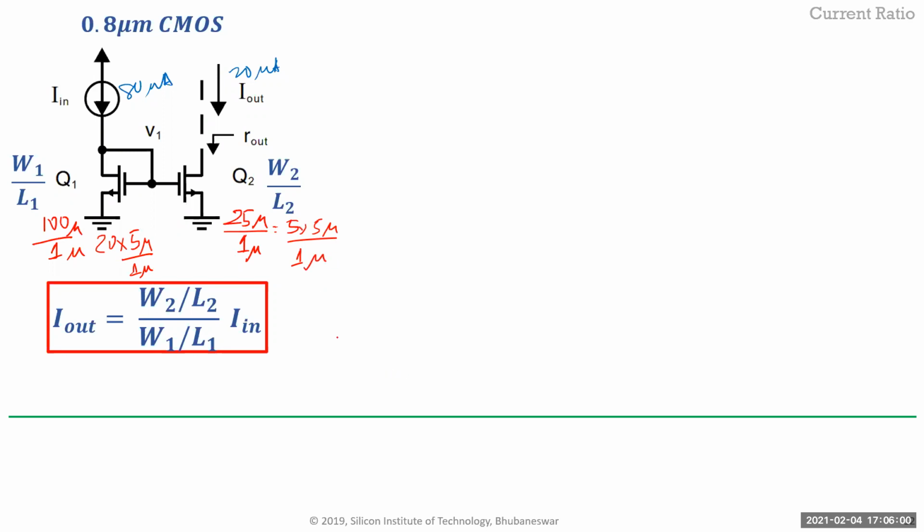That way, when you do the layout, you take a single diffusion, you start interdigitizing, doing common centroid and all that. So that mismatch I was talking about, that delta VT mismatch, will be minimized when you do that. Okay, so you're always going to work with unit transistors, unit resistors, unit capacitors. You're never going to do one big cap here, one big cap here.